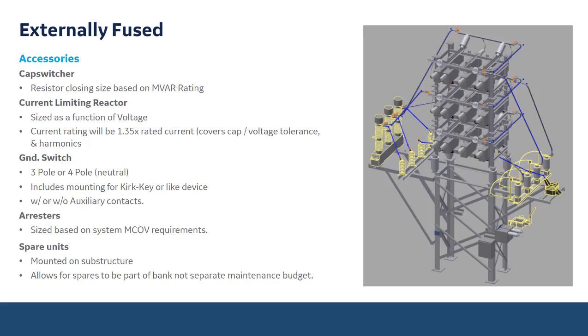Externally fused, some of the accessories we talked about earlier. In order to turn the capacitor bank open and close it, generally we recommend using a cap switcher, and that cap switcher is sized based on the MVAR rating, and really it's the closing resistor size that needs to be sized properly against that MVAR rating.